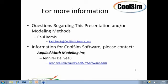CoolSim does allow you to model more granular than that. In our 3.2 version, we allow you to put equipment into the racks and model heat loads down to 1U level and put the loads anywhere you want in the vertical direction. So in this particular model, I did it at the level of average watts per rack, which is uniform, but it doesn't have to be that way, is I guess the point.